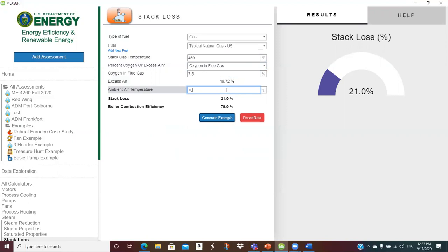Now, if I was trying to calculate an overall boiler efficiency to put into the code, then I would estimate a shell loss. We had some stuff earlier on a shell loss, might be 0.5%, 1%. If I was really doing the best work I could, I'd take an infrared camera out, shoot the sides of the boiler, calculate the average temperature, get the area, do a natural convection loss to the boiler room, and then figure out what percent that was of the input energy, and that would be my shell loss.